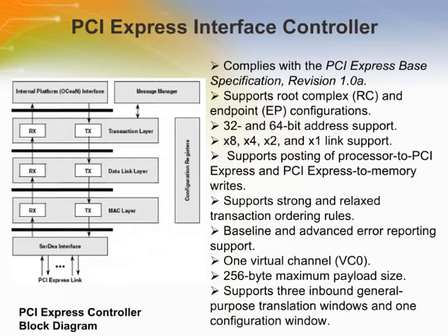As both an initiator and a target device, the PCI Express interface is capable of high bandwidth data transfer and is designed to support next-generation I/O devices. Upon coming out of reset, the PCI Express interface performs link width negotiations and exchanges flow control credits with its link partners. Once link auto negotiation is successful, the controller is in operation.